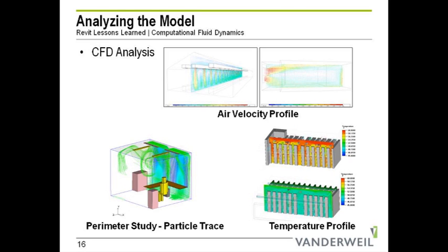That's determined by the type of air distribution, where you're locating the diffusers. It's also determined by the airspeed and the temperature that you're putting into there. So what that shows you is it's very important to be able to make an informed decision on this kind of stuff. And if you're not modeling it, then you're just taking a guess as to how well your building is actually going to be able to perform.